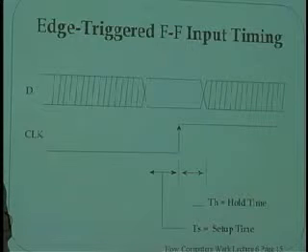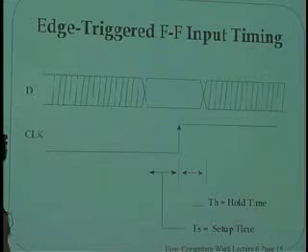And in fact, the oscillators that you buy have specs on them for how much the clock may be off. The clock may run fast, the clock may run slow. And actually, the clock itself, as it makes its transition from a logic low to a logic high, takes a little bit of time. And during that time, you're uncertain what the clock is. And we're going to talk about that too. Okay? So everything is uncertain, but luckily there are bounds on all of these things. And so you're going to get into how all this stuff works.